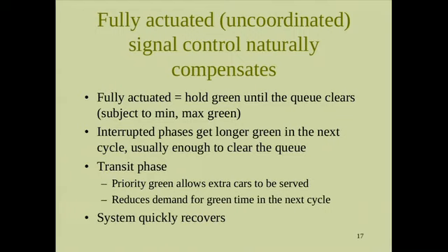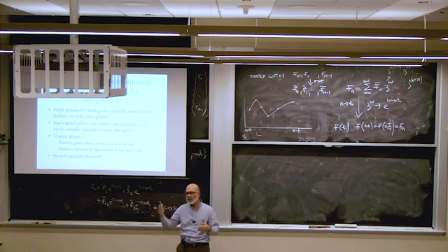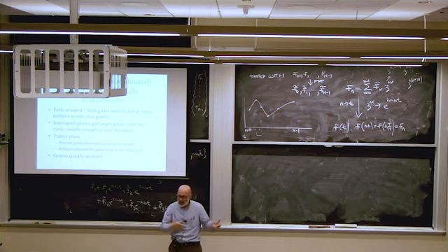And if I interrupt something like that for transit priority, now there's a longer queue. Everybody's been waiting an extra 15 seconds because of this transit priority. Well, when their turn comes up, if they've got more cars, the detector will say, hey, they still have cars. Keep them going, keep them going. Okay, now we finally have a gap. You're over. On to the next one.